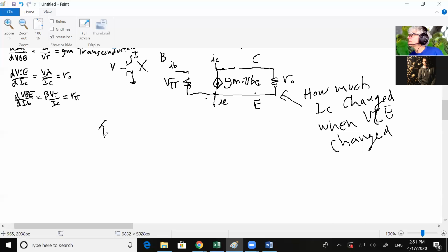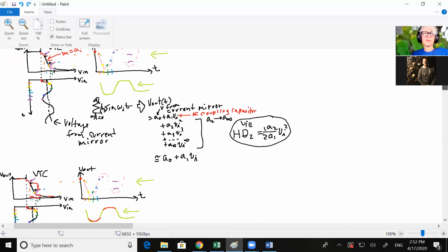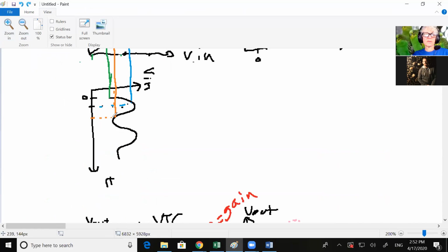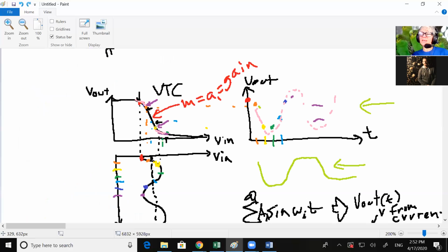Professor, I have a question. Okay, good. As you had mentioned before, when using superposition, you need to do it with linear circuits. So how is that possible when you use elements like capacitors and even a BJT itself? They're not linear elements. So how are we able to do superposition? We fudge. We look at a small enough piece of the graph that it's like a line.